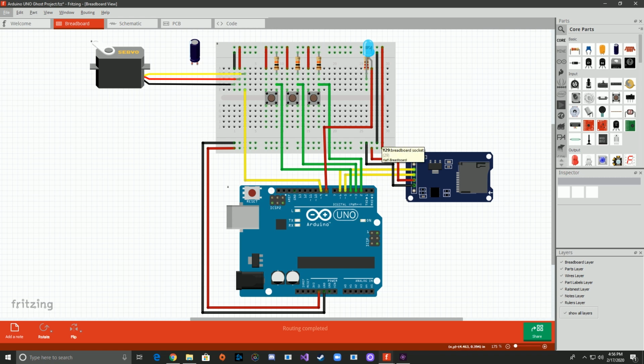And after we've done that, let's come up to the top left corner where we're going to install the servo motor. Now keep in mind your servo motor is going to have different colored wires. However, the pinout should be the same. It should have a ground or neutral, a 5-volt or positive, whatever you want to refer to it as, and then a communications line. In this case, the pictograph has it as yellow. Now this will be connected coming down here to pin 9 of the Arduino, and that's what we're going to attach our servo to so that we can send commands.